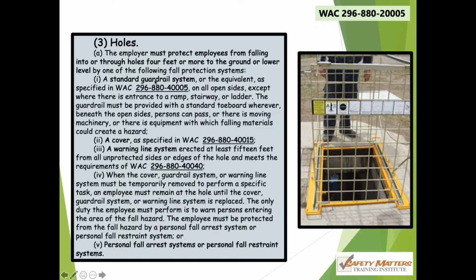How do we protect? Use a standard guardrail system, put a cover down, use a warning line, 15 feet back from all unprotected sides or edges of that hole. Use a PFAS system.